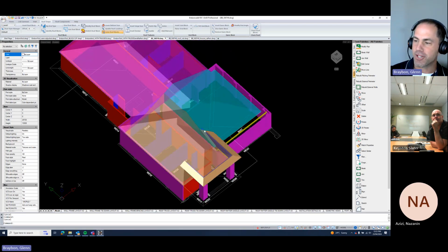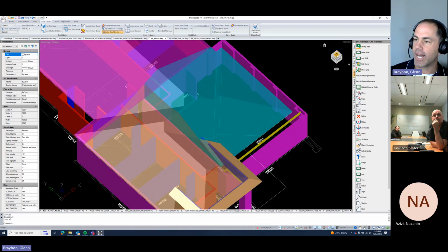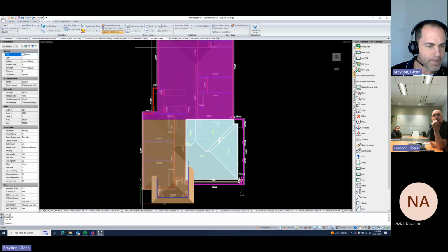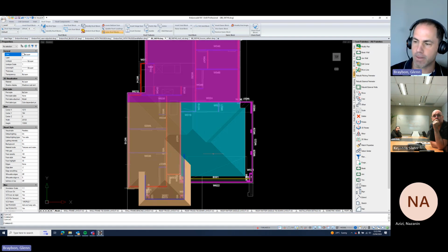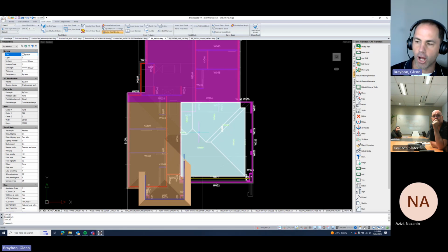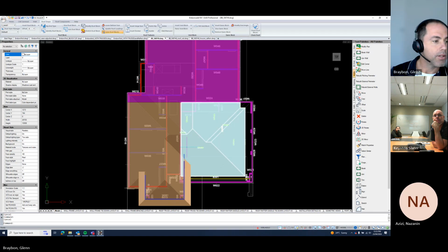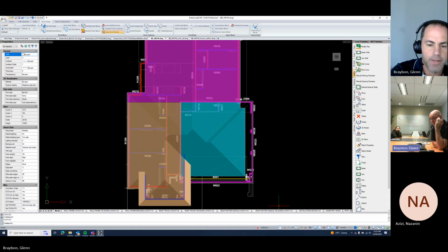Rightio. So I understand you guys would probably at this point join these two roof blocks after you lowered the roof face, maybe. Yep. I'm not going to do that because I know that I can't build trusses in this roof block if I lower it and then join it, which is a known bug that I'm aware of as well. So I'm just going to try and get it to a point where I can lay some trusses out. So when we get the version to try out, that bug potentially will be fixed then.